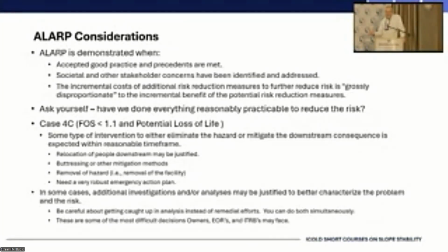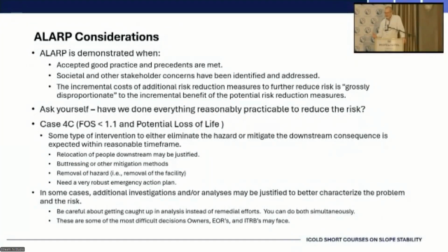And in order to demonstrate ALARP, you need to demonstrate that accepted practice and precedent is met, that all of the societal and stakeholder concerns have been addressed, and that the incremental cost of adding additional risk reduction measures is not grossly disproportionate to the benefit of implementing those risk reduction measures. And that last statement requires a fair amount of explanation that we don't really have time for today.